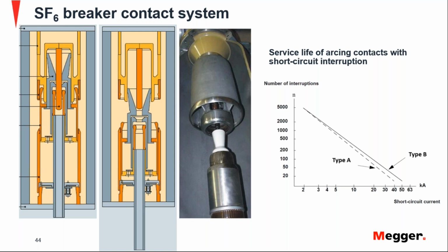So what happens is that during the operation of the breaker, the current is flowing through these two contacts in parallel. Now, the resistance of the arcing contact is much higher than the main contact. So in reality, current circulates through the main contact under regular operation. When the breaker starts opening, at certain point, the main contact opens, but the arcing contact does not open yet.